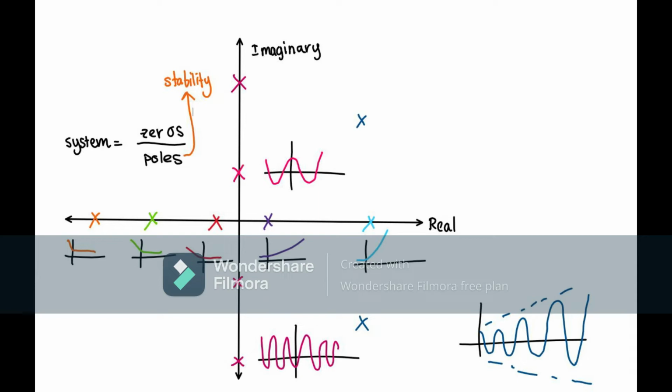The imaginary values represent the oscillating behavior of the signal. These are always found in pairs, and their distance between them represents the number of oscillations found in the signal. The further from the real axis these values are, the faster the frequency of oscillations. The system's poles are directly related to the stability of a system, and their position in the root locus S-plane helps you determine its stability and whether the response will be oscillatory, exponential, and its frequency. This is why the root locus method is really important.